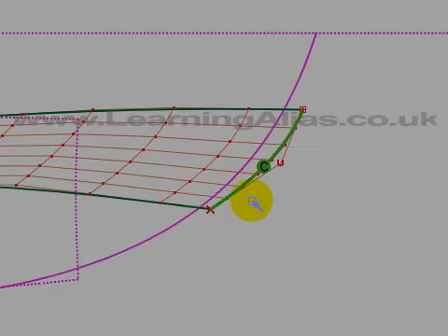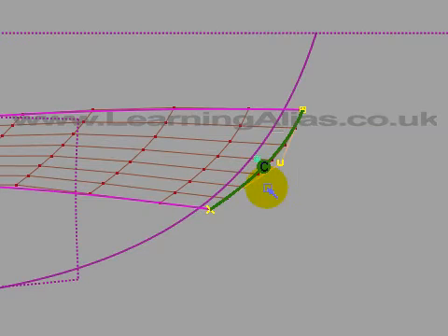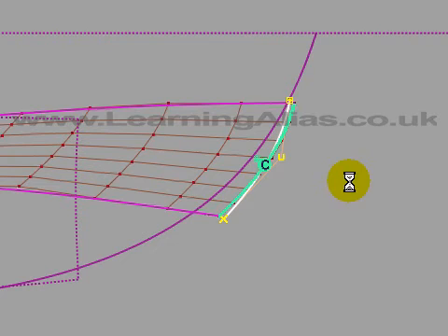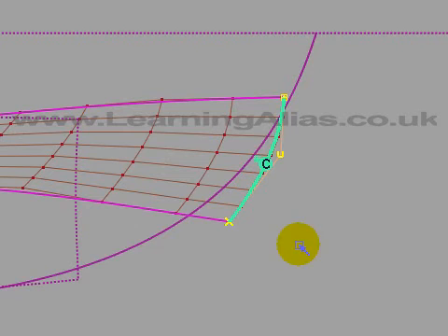Okay. Also, you can pick the curve, center its pivot, and then rotate the curve like so, to experiment with the shape of this footprint, the curve on surface that you're going to build here. And why are we doing all this? Well, we're doing it to get the best highlights that we can.